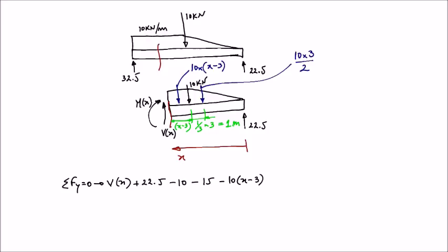So in order for this to be in equilibrium, this needs to be equal to 0, and from this equation we can get the transverse shear force as being equal to 2.5 plus 10(x minus 3).